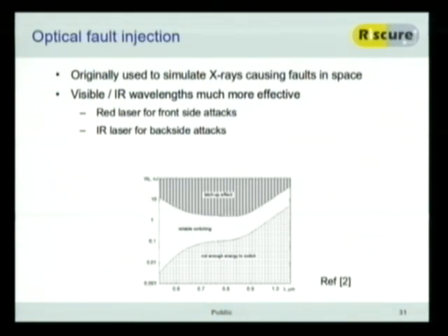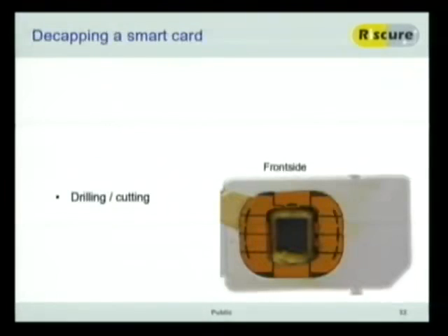Whereas if you're on the back side, you're looking at the substrate, which you have to penetrate all the way to the gates, and there you need to cause a fault. So that's why we use infrared lasers for that. We need to access the silicon to get to this. I've actually heard of some guys who are able to flash right through a card, like they don't even need to open it up. With a flashlight, you can just glitch all the way inside there. We try to have a bit more control, so we actually need to open it up.